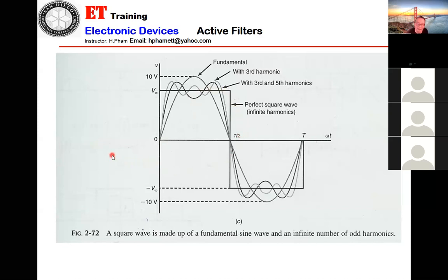You cannot get any different frequency. So that's why on the oscilloscope, when you see 1 kilohertz, you can get only 1 kilohertz. F maximum and F minimum will be the same. So the bandwidth of 1 kilohertz will be 0 hertz.